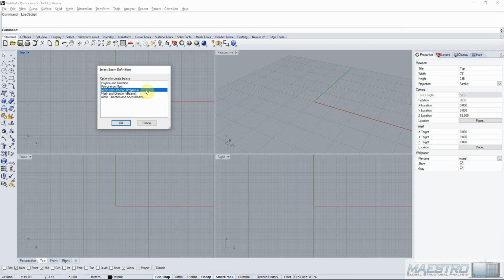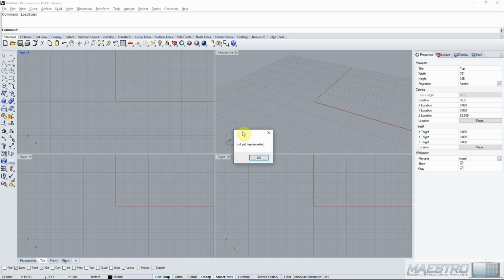In option 3, Polylines, it stops there, and the polylines are available for the user to edit and then go back and export using option 2, Polyline on Mesh. In the fourth option, Beams, it continues on and actually exports all of those extracted polylines as beams and then presents the user with the option to either save those polylines for additional editing and re-export or to just delete them altogether. Finally, for the last option, the placeholder, if that were to be executed, the user will simply get a notice saying that it doesn't exist yet.